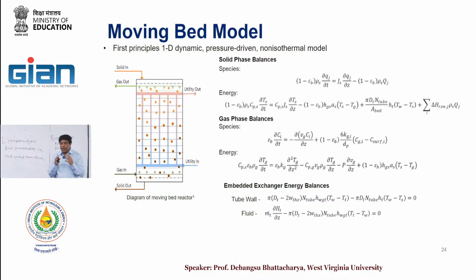If you are saying, I want to regenerate every 10 minutes or every half an hour or every 45 minutes, that means every 45 minutes you are heating up the bed. So you need an effective heating system and that amount of heat, and that actually hurts these beds.